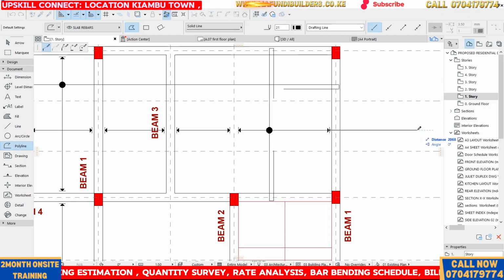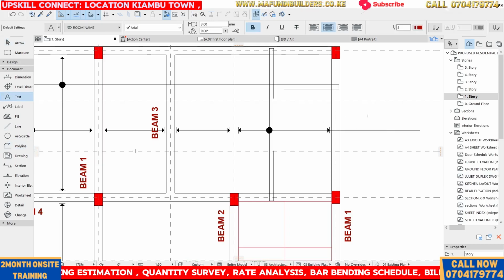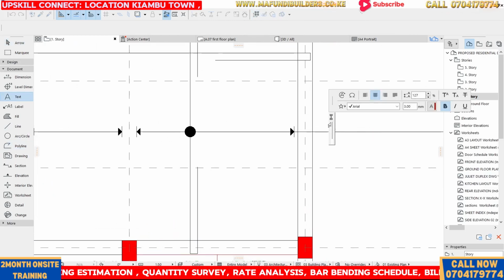So I'm supposed to come here and draw a line. This is called calling out, or the annotation. Then pick the text tool. Here I'm going to write, for example, we have said 15 T10, that I will have a bar mark, probably 01, and then I'm going to have 150.